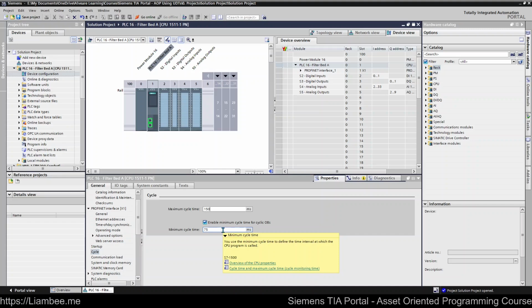And it's not only that, it's that the asynchronous access points won't be the same for every single scan. And you can't guarantee anything involving HMI comms in terms of when that will take place. There will still be interruptions, and you don't really need to accommodate for them if you've written your code correctly. But setting a minimum cycle time seems to improve that stuff quite a lot.